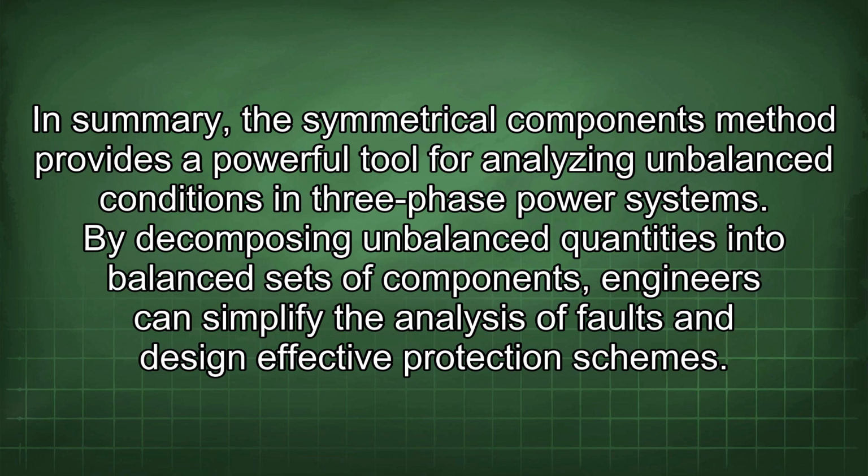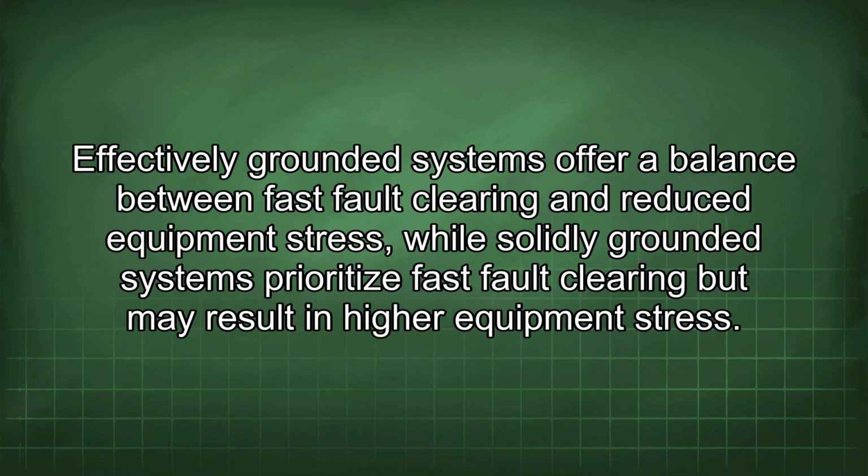In summary, the symmetrical components method provides a powerful tool for analyzing unbalanced conditions in three-phase power systems. By decomposing unbalanced quantities into balanced sets of components, engineers can simplify the analysis of faults and design effective protection schemes. Effectively grounded systems offer a balance between fast fault clearing and reduced equipment stress, while solidly grounded systems prioritize fast fault clearing but may result in higher equipment stress.